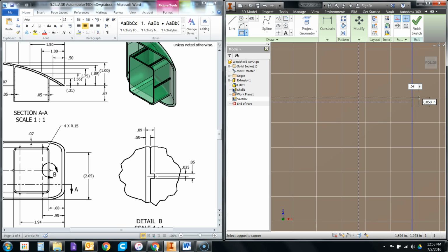Now if I had to place another one that was the same size somewhere further along this vertical line, I would make sure that instead of having to put in this 0.04, I line it up with the same dashed lines so that I know that it's 0.04. And you can even tell that with the other dimension that's not being typed in by me, it's already set at 0.05 because I have somewhat geometrically constrained it to the other rail on the left side of this feature. And I'll apply it. And once again, I have forgotten to turn off construction lines before I start that rectangle.